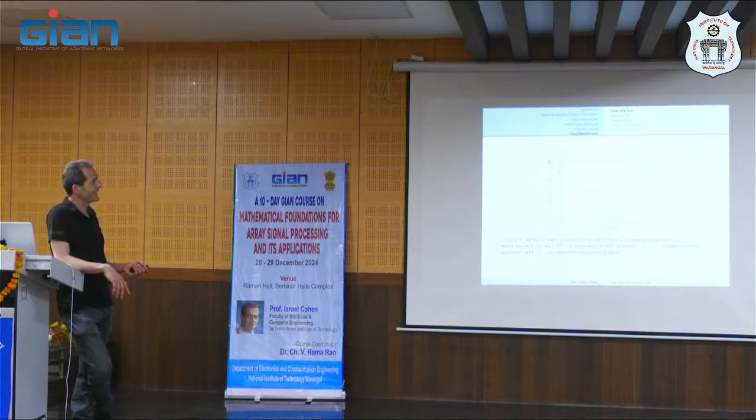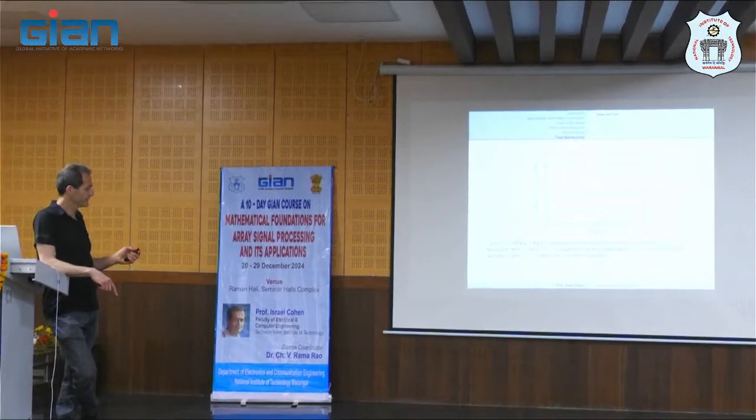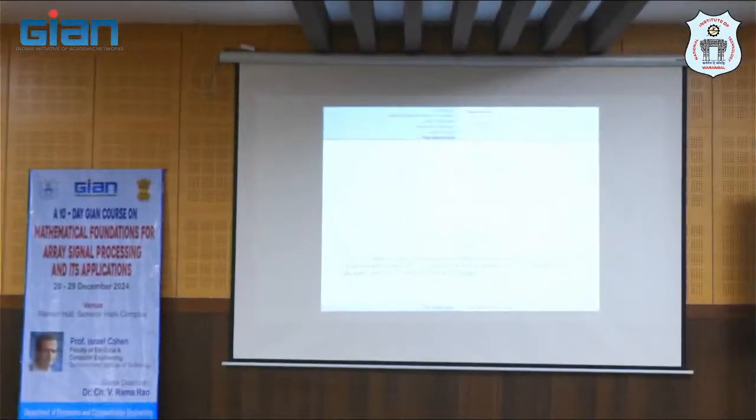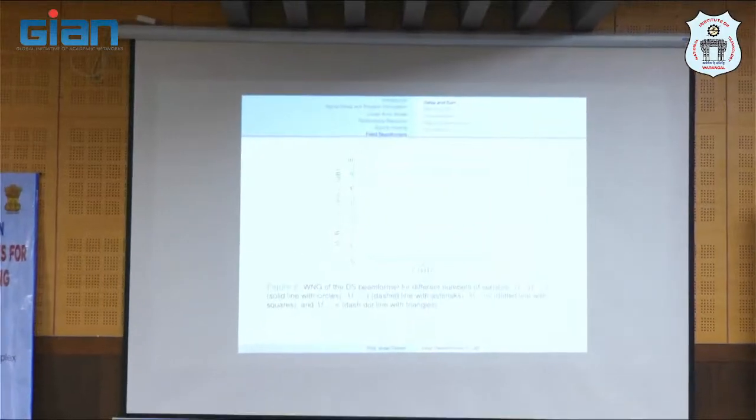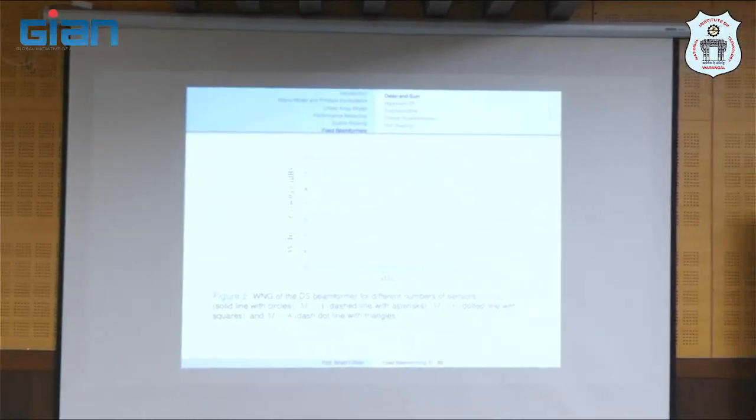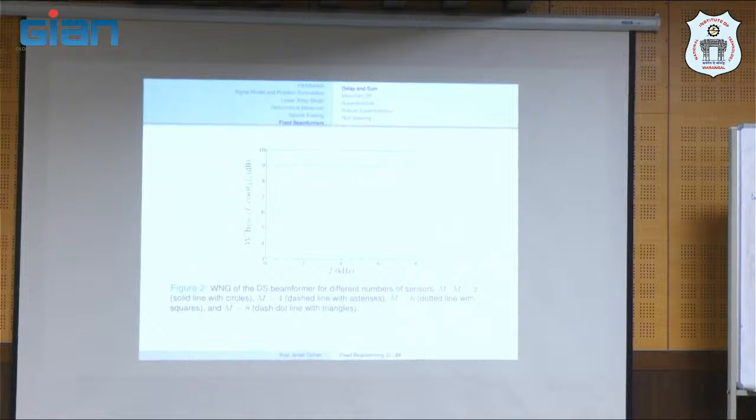Also, we see that the gain in SNR is simply M, because this is the maximum possible white noise gain, and it's independent of the frequency. Here it's in dB, so 3 dB is a factor of 2, and so on.